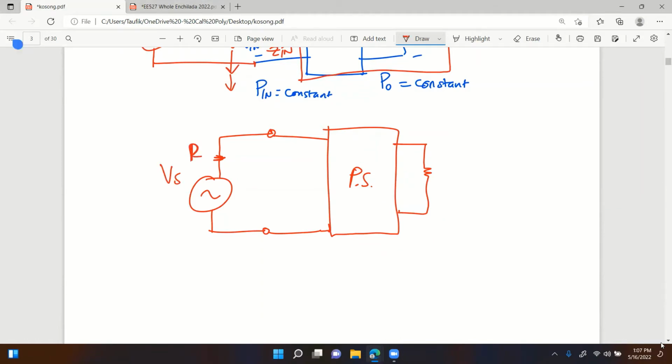An input capacitor, an input filter. Yes, exactly. Input filter. That's what we're missing, right? So in reality, that's what we put in between the two. Input filter. That could cause a problem, right? Why? Because the input filter has impedance, negative, right? No, the negative impedance right here. Sorry, yeah, that's the negative impedance right here. The filter itself doesn't have negative impedance, right? But the input impedance of the power supply is negative, right?